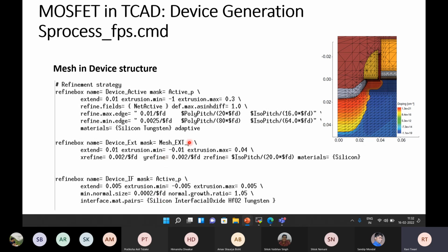The professor was saying that the meshing was important, and this is the picture that can explain it a little better. When we say meshing, these are the points in the space where all the semiconductor equations plus the physics that you want to check are going to get applied and solved. As you already know, conduction happens mostly towards the surface, and the channel is formed closer to the surface, not deep in the bulk. That's why the mesh points here are at maximum, because we want it to be very dense so that it can have very high accuracy.